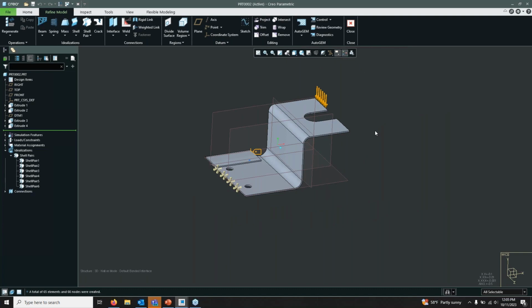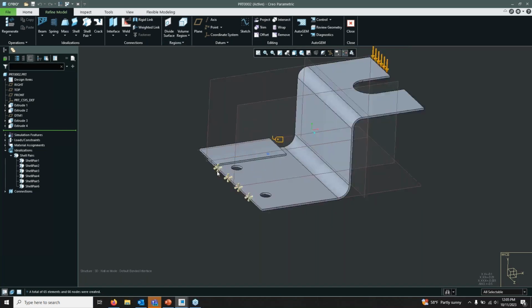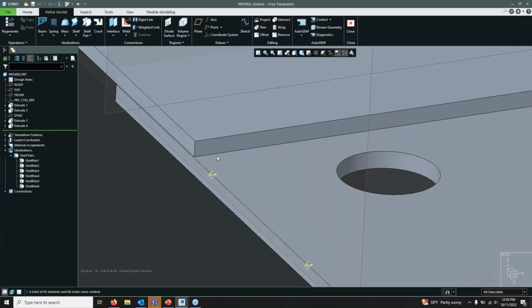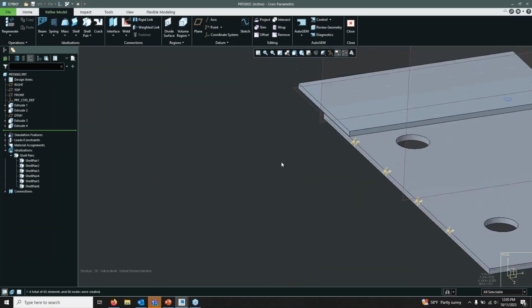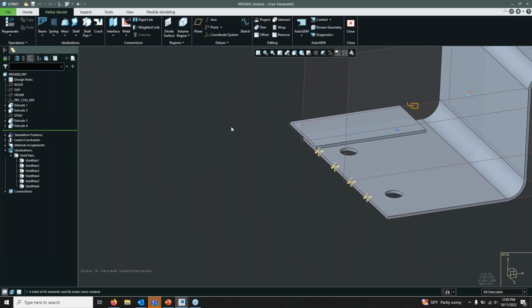Okay, so that is shells or idealizations in general and welds. As I mentioned, if you want to model actual welds, so fillet type welds where I would weld along this edge right here to join these two together, the most accurate way to model that is not going to be using this weld feature. And this is where I would recommend the Army paper. So Google, US Army simulate weld paper, and you will find it.